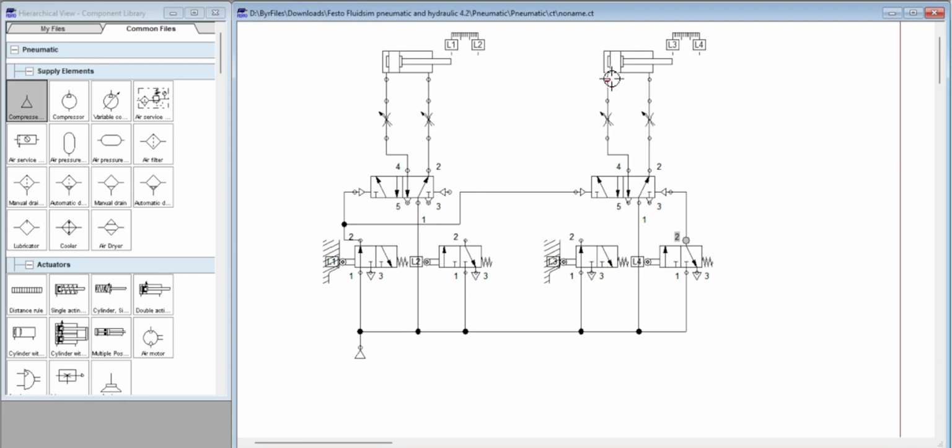So this cylinder will wait first for 2.0 to extend in order to release L3. Because if there are two pressures on the 5-way valve, this will not operate. There can be only one pressure present in order to assume the path of the pressure to the cylinder 1.0.